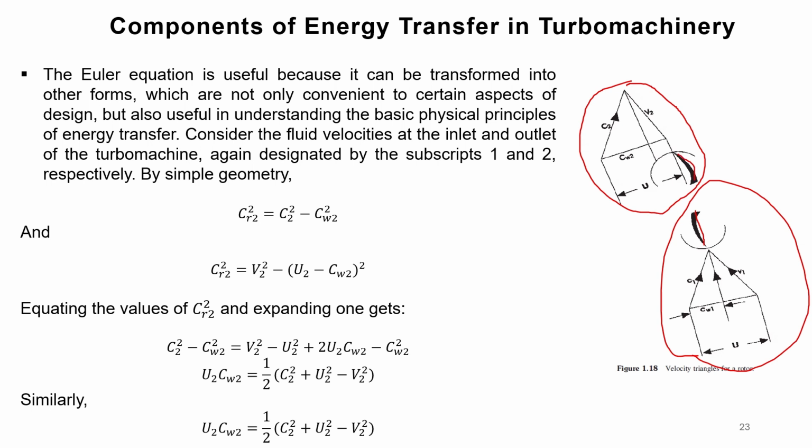So here in this case we have always the radial component. See here represents the absolute flow velocity. In the examples of this lesson, the absolute flow velocity was denoted as V, but in the theory of this lesson, the absolute flow velocity was denoted as C. Just be aware of that, and I have written it explicitly on the example. I have stated that I am using the letter V as the absolute flow velocity, but here we have the absolute flow velocity as C, and we have always the radial component normal to the axis of rotation.